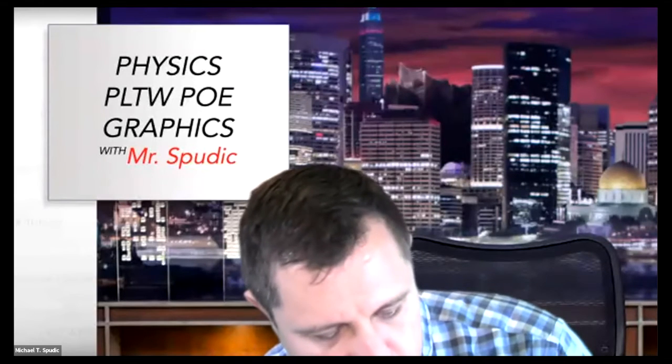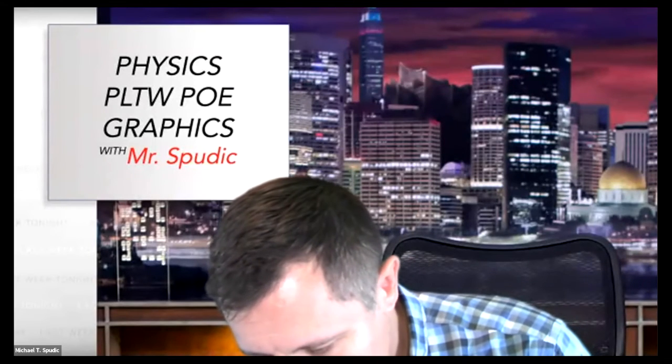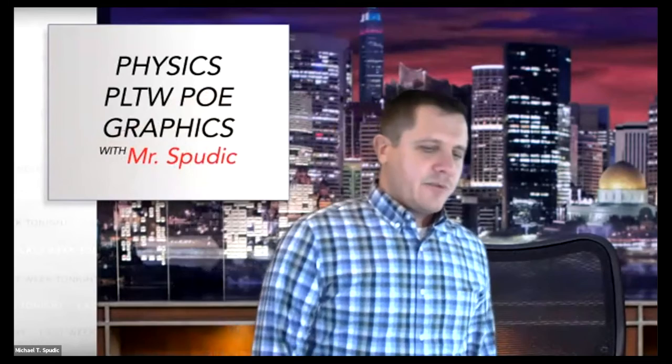So now let's look at these numbers here. I know I'm not sharing my screen anymore, but hopefully you have your screen up. Look at the modulus of elasticity for Douglas fir versus plastic. So we see the two of them. The modulus of elasticity for Douglas fir is 1.8 million PSI. The modulus of elasticity for the plastic is 410,000 or 419,000. Okay, so everybody try to understand this.